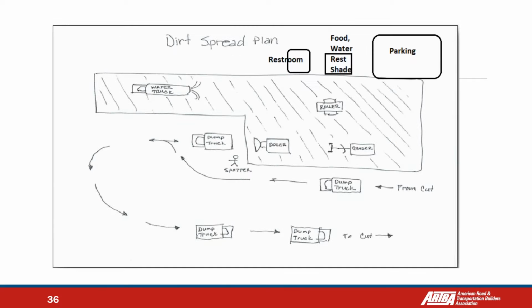And maybe you can say, hey, of course you need to put all these resources near the workers on foot. This area with chevrons are the areas for workers on foot. The other area, in which we can read the dump trucks and the lanes, are for traffic. So we want the workers on foot to have access to all these resources near to them, in a way in which they don't need to cross any traffic lane to have access to these resources.